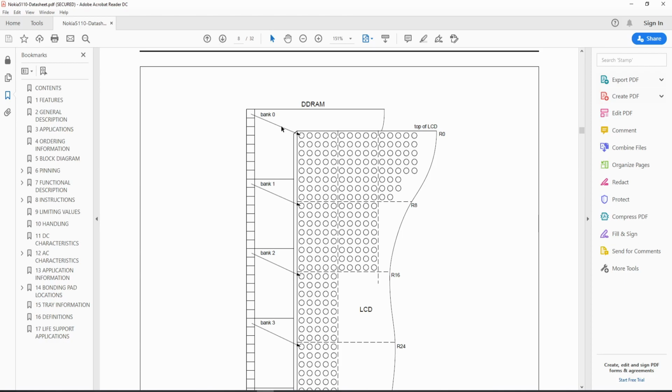Imagine I'm sending a byte 100000, which is 1. Then we will have one here. This LED will be on, and all the other LEDs will be off. If my next byte is 2, then this one will be off, this one on, and all the rest will be off. We will really see this more with the example application, but it's simple like that.